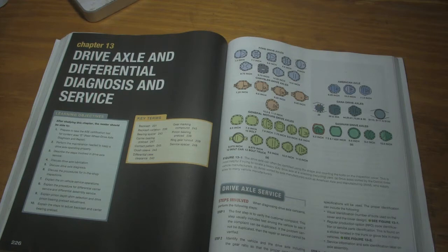issue where the customer is complaining of like a chattering noise coming from the rear end of the vehicle. The chattering noise might be originating in the limited slip components, and technical service bulletins might point you to replace the entire limited slip clutch pack rather than take the diagnostics any further. And so the value of technical service bulletins is really, really important to understand when it comes to diagnosing these